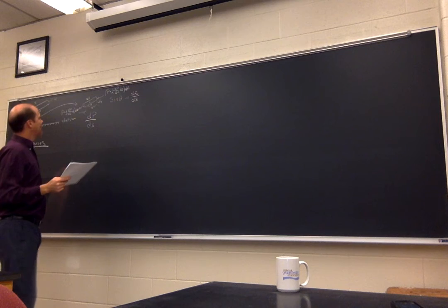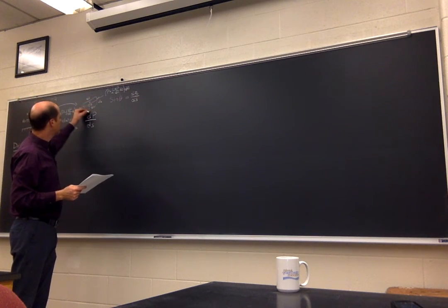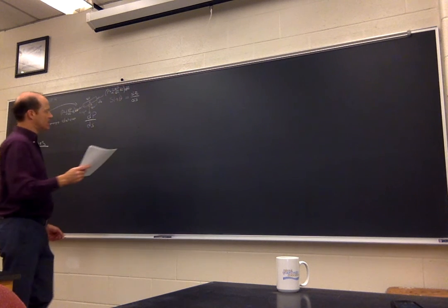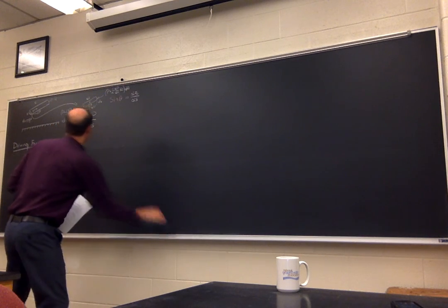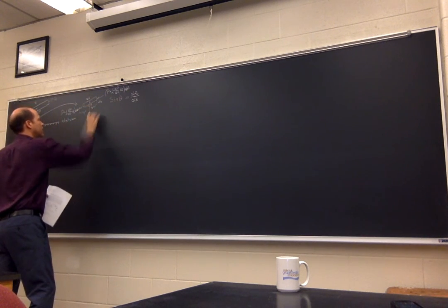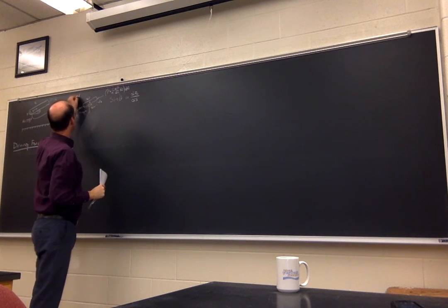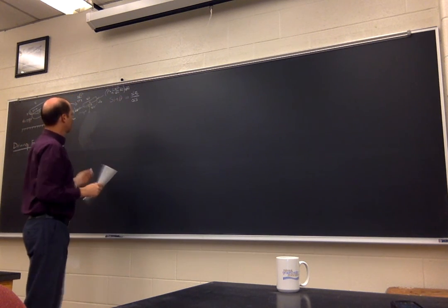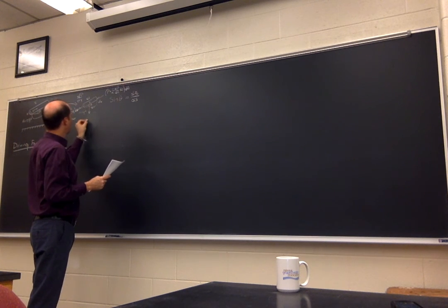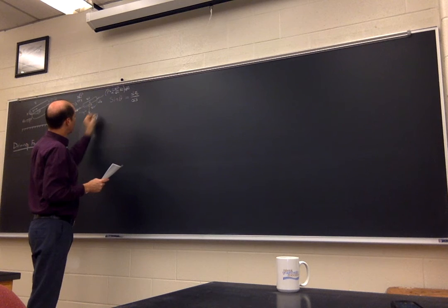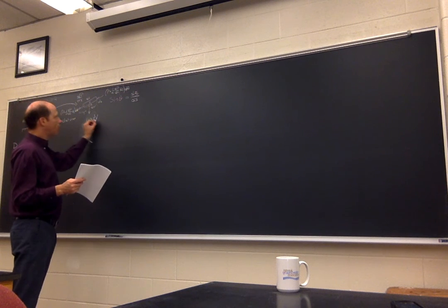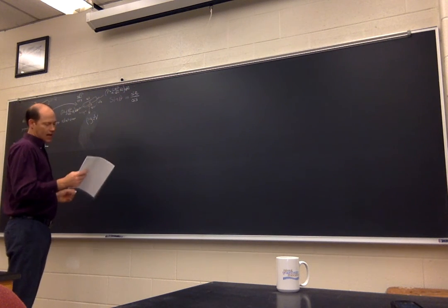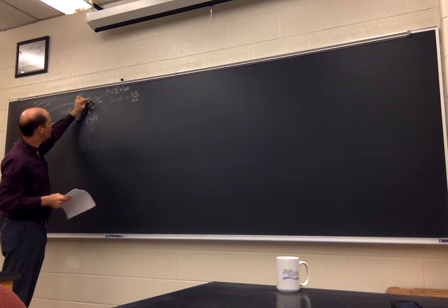The other force that's acting on this system is the one that is due to gravity, and that is what is pulling this down, which is rho g dV. So let me put dP/ds here as the pressure gradient. So the gravitational force now is rho g dV. That gravitational force has components that are acting in the ds direction.